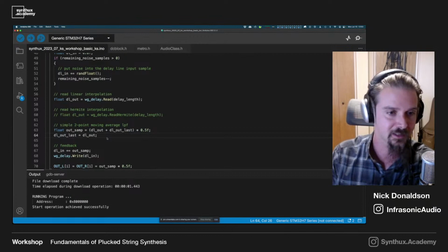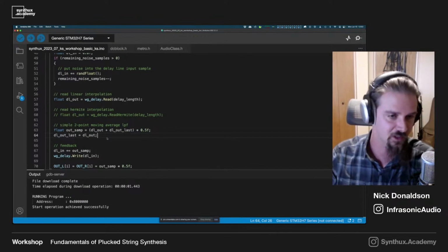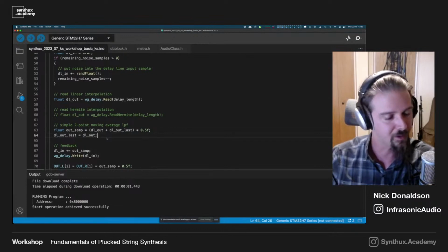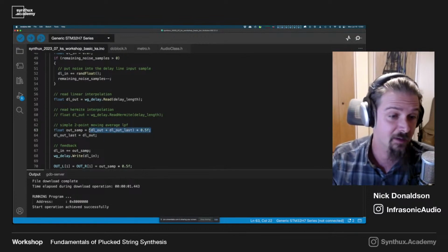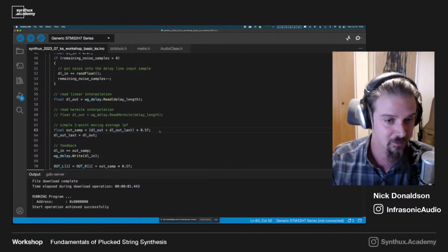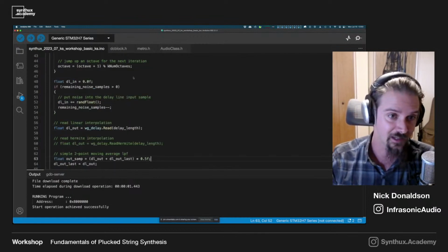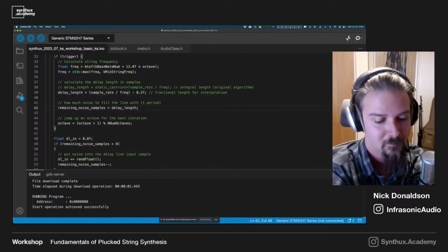Let's take two samples and interpolate linearly between them to get an approximation of the value that would fall between those two samples. In this case, it's exactly the same as linear interpolation by half. So we're just equally weighting the two samples. So this is actually an additional half sample of delay in our delay line, which is why we're subtracting here 1/2 a sample to compensate.